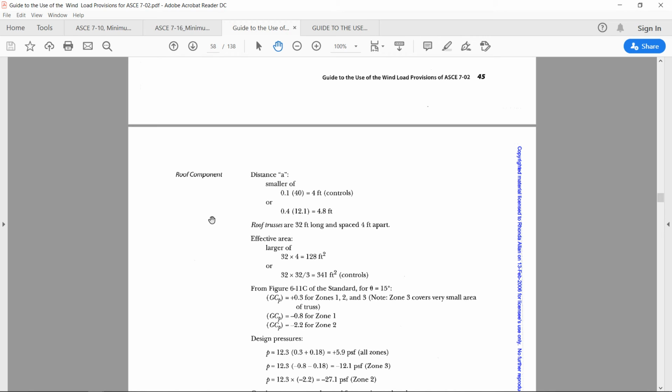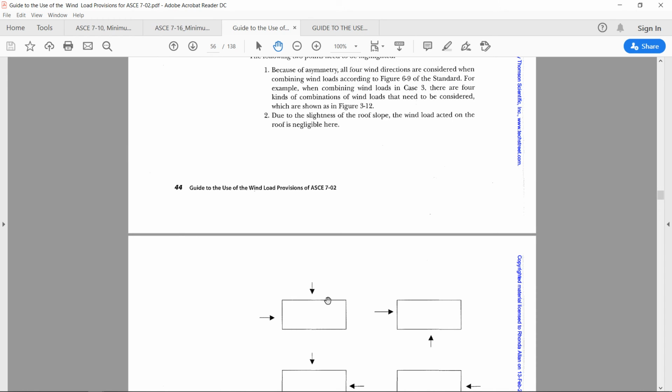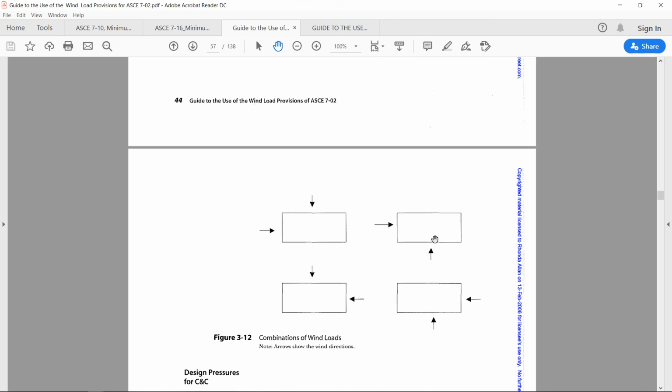That means you have to design the building for all the possible wind directions and for all the possible surfaces, and then ultimately you have to define the wind load cases and combine them into mutually perpendicular directions. As I have shown just before, take two mutually perpendicular directions at one time, and you can define these four simple load cases. So hopefully it is clear how we define the wind load cases for an irregular shape building.